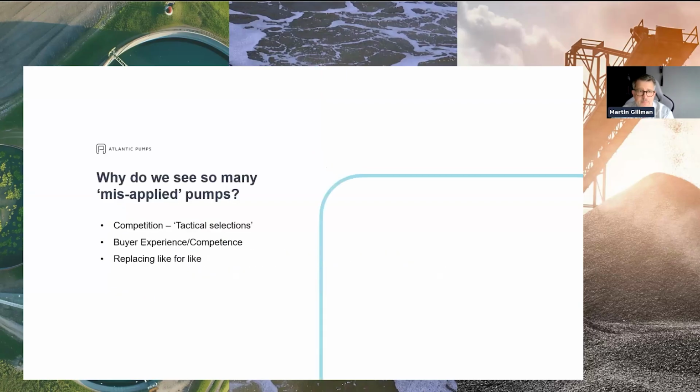So just remember those. And I'll just be honest, why are so many pumps misapplied? Competition. Sometimes in competitive situations, manufacturers will reduce their pump size in order to reduce their price, in order to win an order. It's that simple. Be bold about it, be honest about it. And so that's often how it can happen.